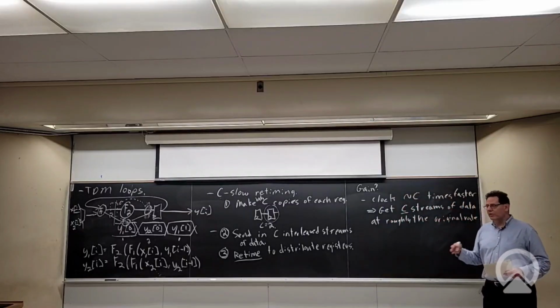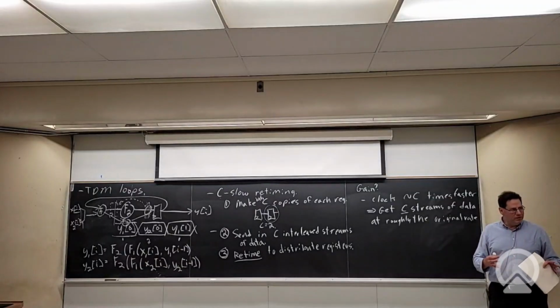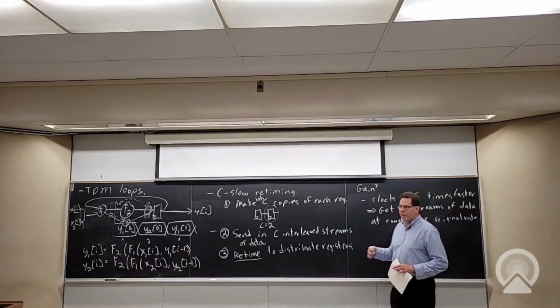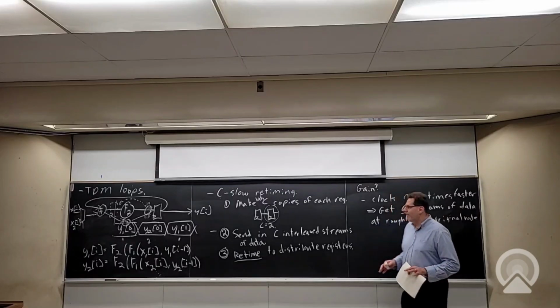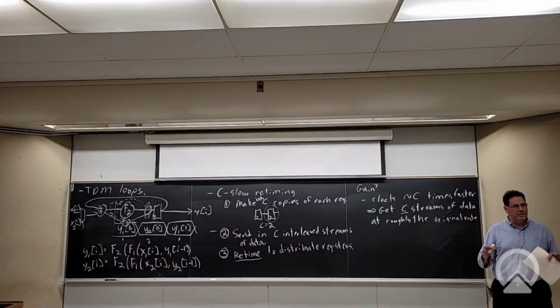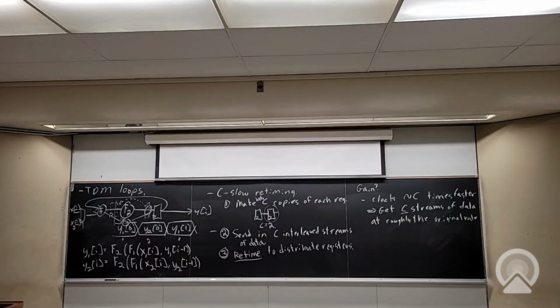Yeah. In lab 1, you don't have to do this, but you'll see there are different compute styles. One of those compute styles, we've already talked about, the streaming ones, okay? And another compute style is one where you try to share operators. It's a little bit more like a CPU, but not quite. You can time domain multiplex that. That naturally winds up with loops. You don't have to do this, but some students will wind up time domain multiplexing because they'll apply this optimization to get more throughput. But the assignment doesn't actually ask you to do that, so you only do that if you just think, this is fun, I want to try it.